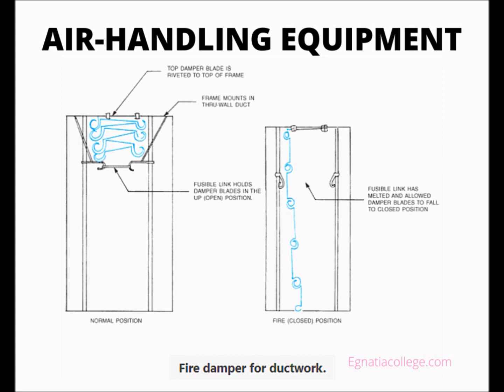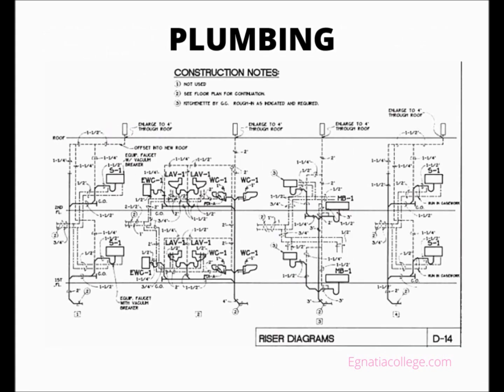Above the second floor louver, the duct is 8x8, and at the second floor ceiling, it is offset an unspecified distance into the storage room, where it turns up to EF4 on the roof. The reason for the offset is that it would otherwise be too close to the other duct, such that there would not be enough room for both exhaust fans on the roof.